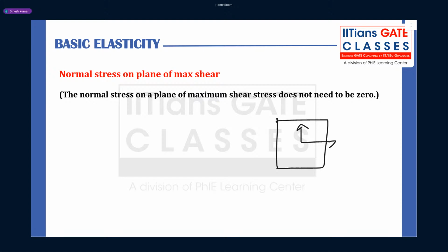Minus, right? So how will I write the angle, clockwise or anti-clockwise? We are getting a negative value, so how will we draw the angle, Gopal? Clockwise. Clockwise, right? Because when theta is positive, then it has to be anti-clockwise. So theta we got negative, right? So that means now my plane of maximum shear will be like this, okay, and this is theta.